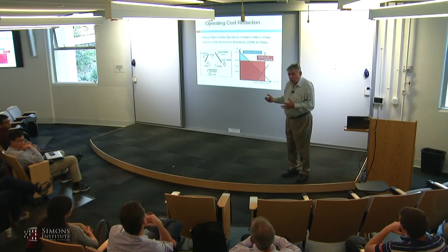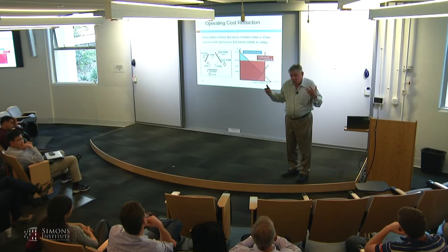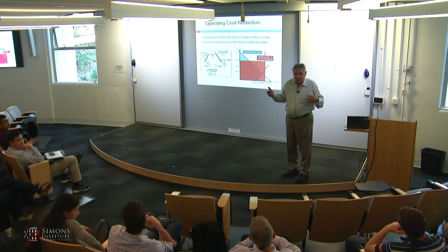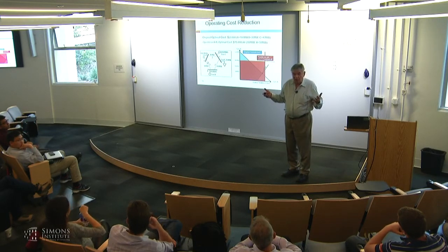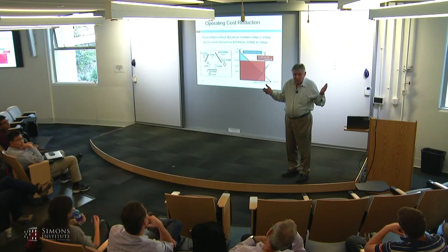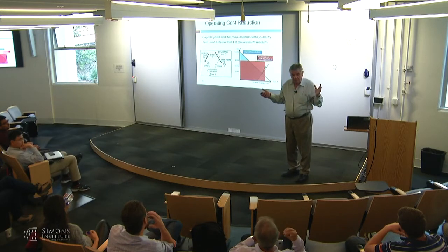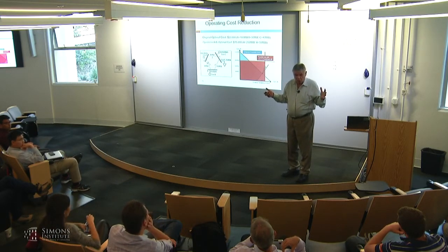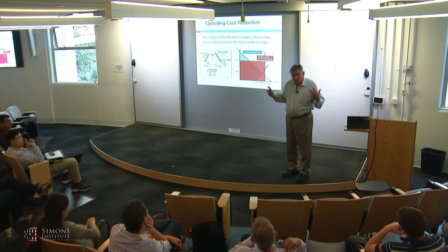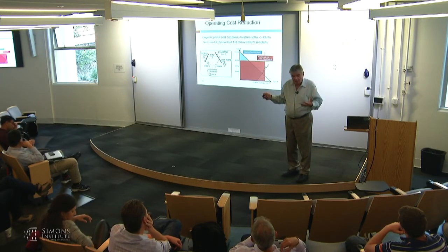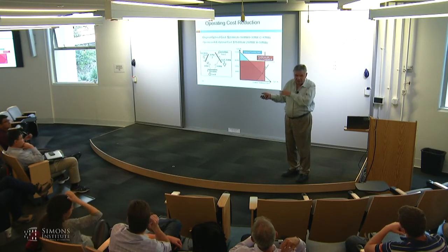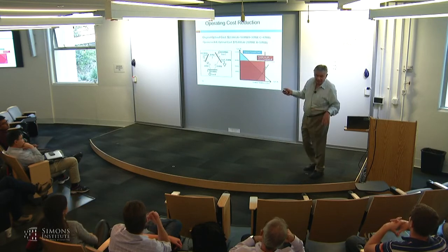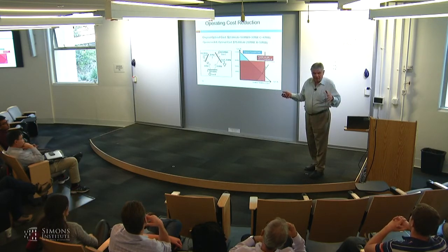Well, we do it for a short time, but in a large network, we can actually also enforce reliability. And the reliability constraint usually in electricity is n-1, meaning that if any line fails, the system can still support its load. So we can impose that as an additional constraint. I'm going to abstract from some of that in the examples, but we have done that.